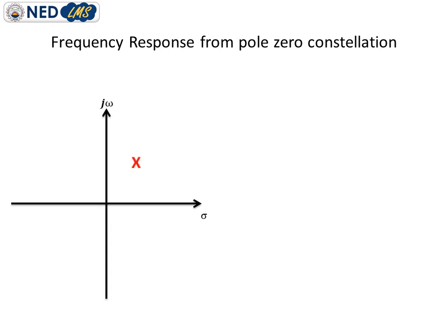Both are forming the S-plane, and it is very interesting to note that the poles of this system lie along the right hand side of the S-plane. So we can easily comment that this is an unstable system.